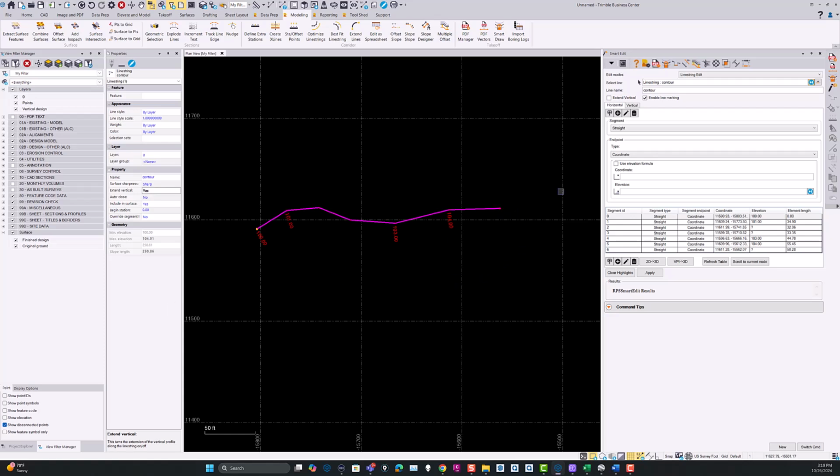When we look at this, we've got two tabs just like the Linestring Editor. At the top, the mode that we're in is Linestring Editor, and we can say we're going to edit this line, which is the one I created here, and the line name is shown here, and we can edit the line name should we want to do that. So if I want to call that now embankment, I can change it directly in the editor.